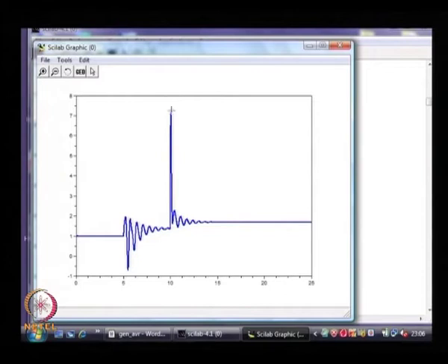Okay. Now, EFD is able to take on values as high as 7 because the limits are very high. Excitation system of this kind has high ceilings. Okay. So, we are able to force the field to a very high value. That is of course, as I mentioned some time back, because the field winding is a very slow acting system and you really need to push it a lot in order to make it work faster. Okay. So, this is the way field voltage changes. Remember, field voltage is no longer constant because it is being changed by the automatic voltage regulator.